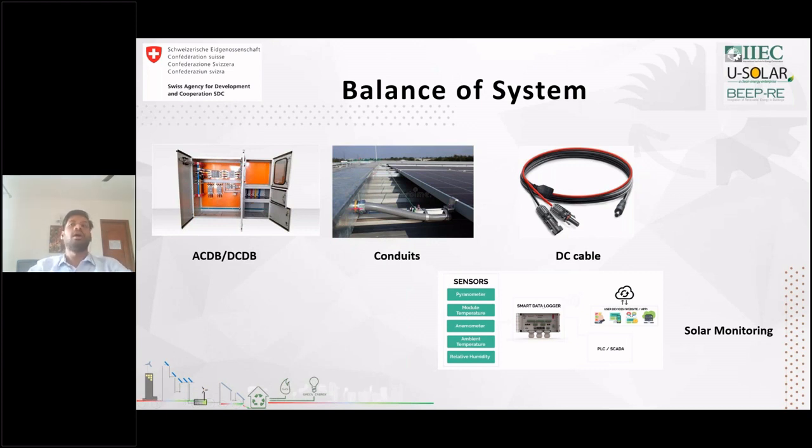So once you have a solar system installed, we have approximated the generation for your area. How do you monitor if a solar plant is working optimally or not? For this verification, we make use of what is called solar monitoring. Solar monitoring consists of a data logger, and we integrate this data logger with pyranometers.